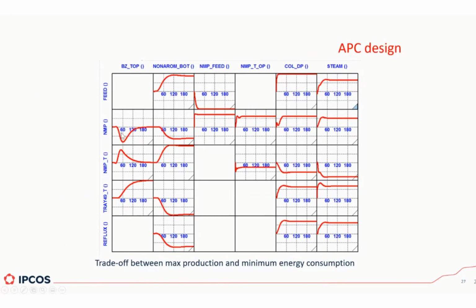So yeah, using it too much meant that maybe you would not be able to cool it down as much as you could. The solvent is in any case a liquid going in the column, so it meant that your column delta P would increase, driving you closer to the constraints of the plant, of the column. The steam consumption was also increased by that. And same thing we see with some other variables.